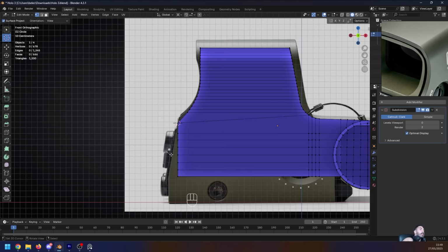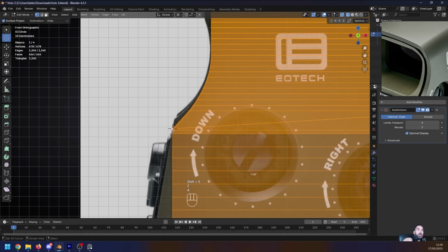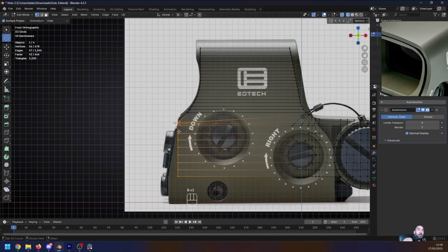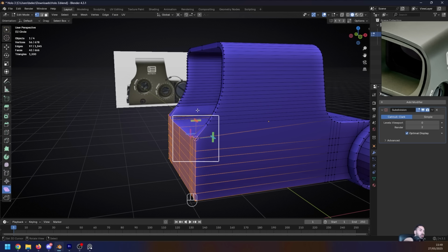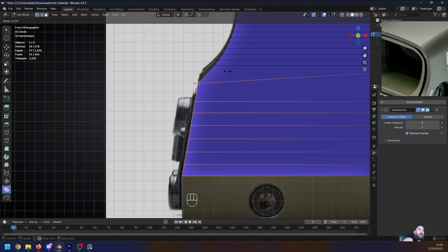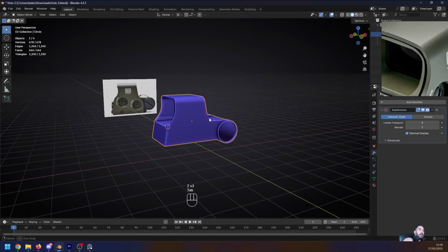We also have to place this at a bit of an angle, so we're gonna place the 3D cursor onto this vertex at the top up here. Select the entire surface, activate your shear tool, set the pivot point to 3D cursor, and then just shear that a little bit until you get something like this, and now the inner shape is more or less ready to go.